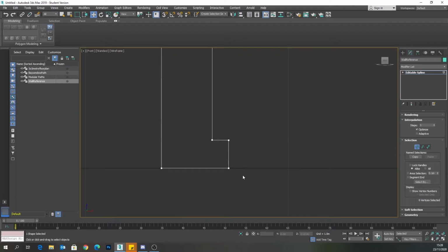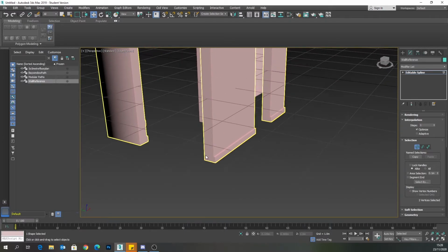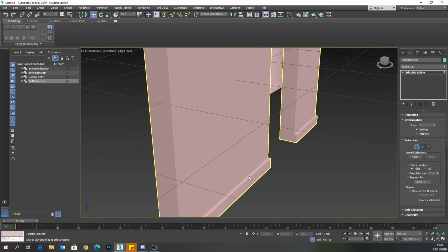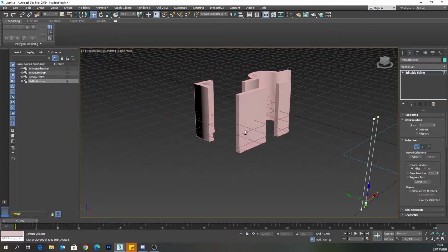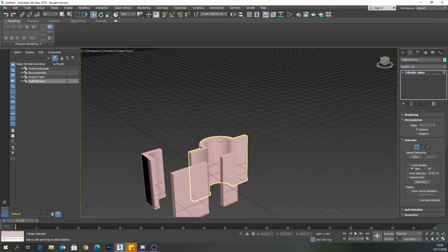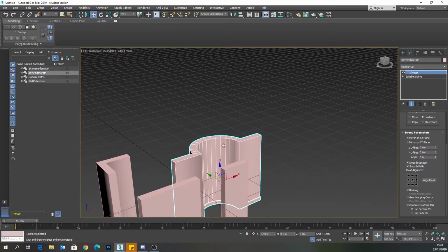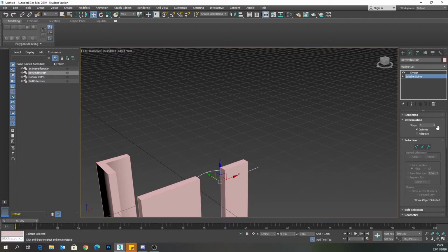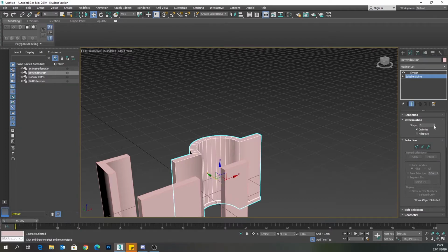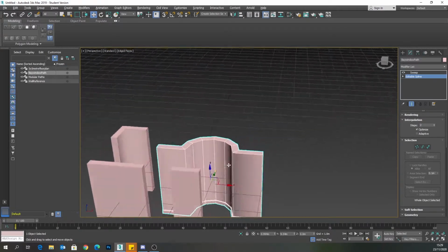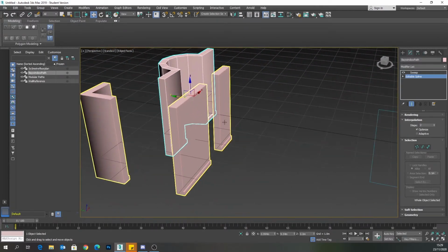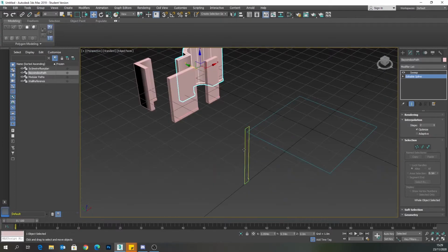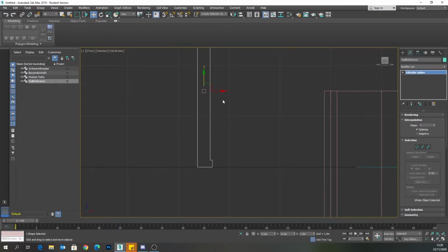Now, if that's a little bit too far along, we can move them and get the visual that we want and keep taking a look. I'm just toggling through front and perspective views just to check what I'm getting. Now, if I want to add some more detail, if we lower the interpolation on the bay window, the interpolation on the actual path will affect what it does along the path. The reference will affect what it does for the shape.